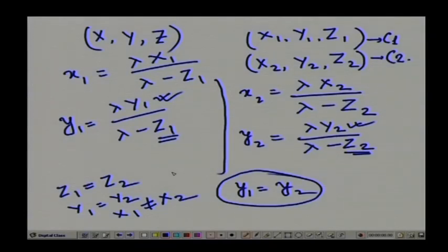So, if I pick a CL belonging to row I in the left image, the corresponding point CR in the right image will also belong to the same row I. So, for a given point, I do not have to search the entire right image to find the correspondence; I will simply search that particular row in the right image. This saves a lot of time while searching for correspondence between a point in the left image and the corresponding point in the right image.